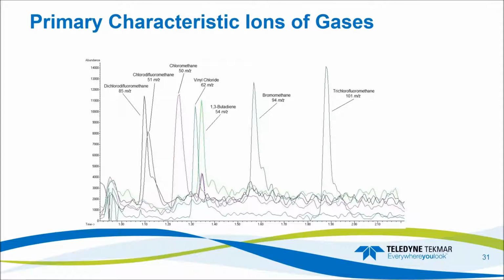So here's a chromatogram of the first 6 or 7 gases here. And we're looking just at the primary target ions. But again, we see that we have adequate separation for our target ions for these gases, and we have nice peak shapes. And this was done in, I believe, a 0.5 PPB standard. So even with a somewhat potentially diminished purge efficiency, we're still seeing good recovery of our light gas compounds with minimal water interference, thanks to the new water moisture control in the Lumin.